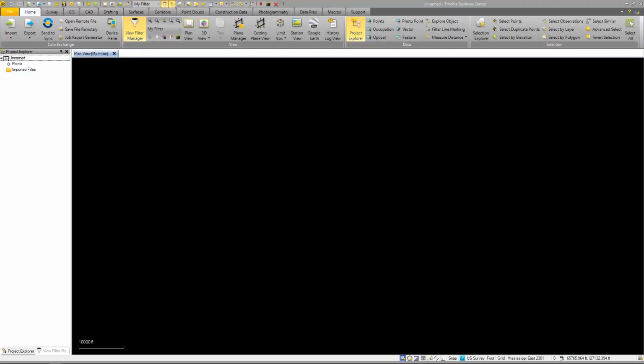Okay, so let's close all this stuff down. So right now, let me find, here's that job file. Okay, so the way this is going to work is you have a job file and then you have what I call a related file folder. In this case, it's called training. So I've got a folder called training. Both of those are on the data collector under your Trimble data folder, which is under program data, Trimble data. It's under your project, blah, blah, blah.